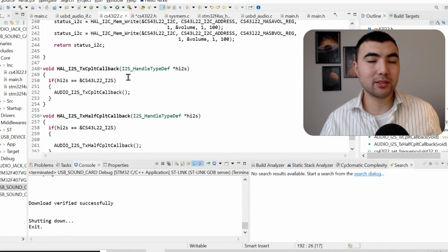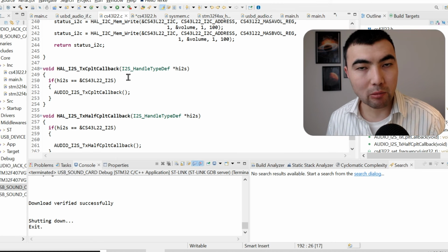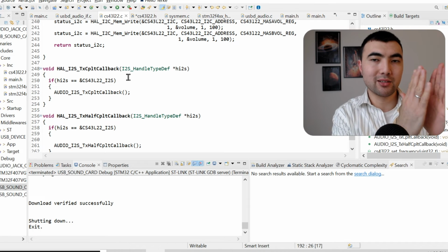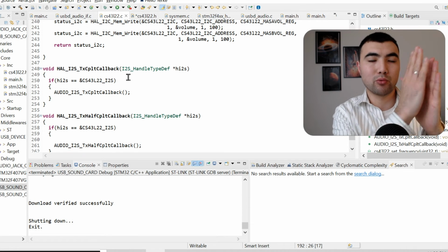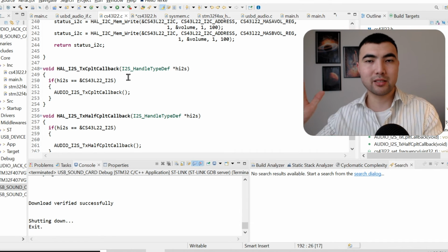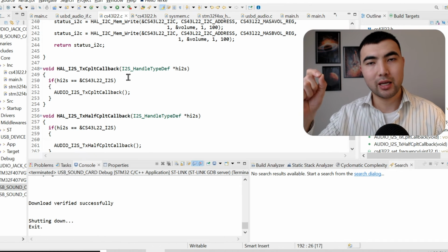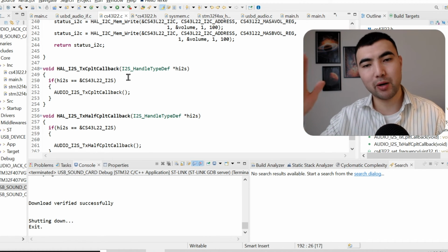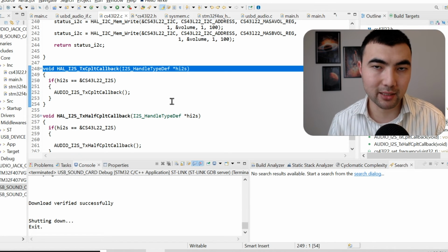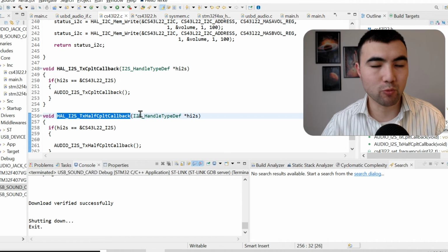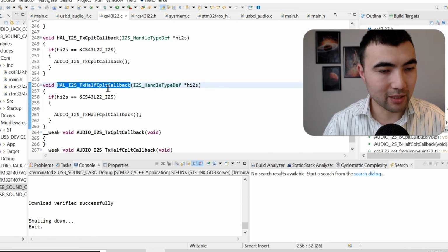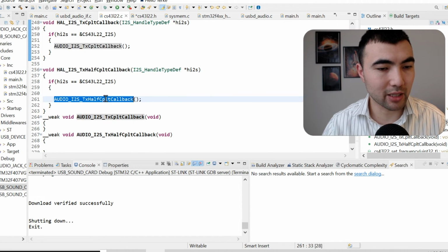when using DMA, it is important to use the callback functions. So we have the buffer, for example. So I2S will start streaming that data to the DAC. So at some point it reaches the end of the buffer and it starts from the beginning. So to capture this event when the buffer is over, we have this callback function which is invoked automatically. Okay, this callback function when the DMA reaches the half of the buffer. And when this happens, we have these functions inside to be called.